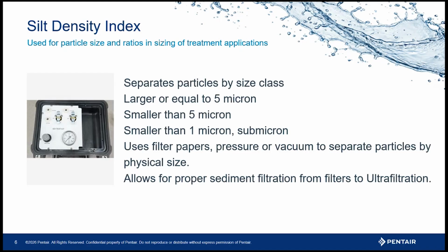Some of them may require aggressive oxidation via chlorine, hydrogen peroxide, or ozone. Some of this may depend on what else is in the water. You may want to oxidize iron at the same time in situations like this. Other dynamics may be associated here as well, so always take that full water analysis into account.